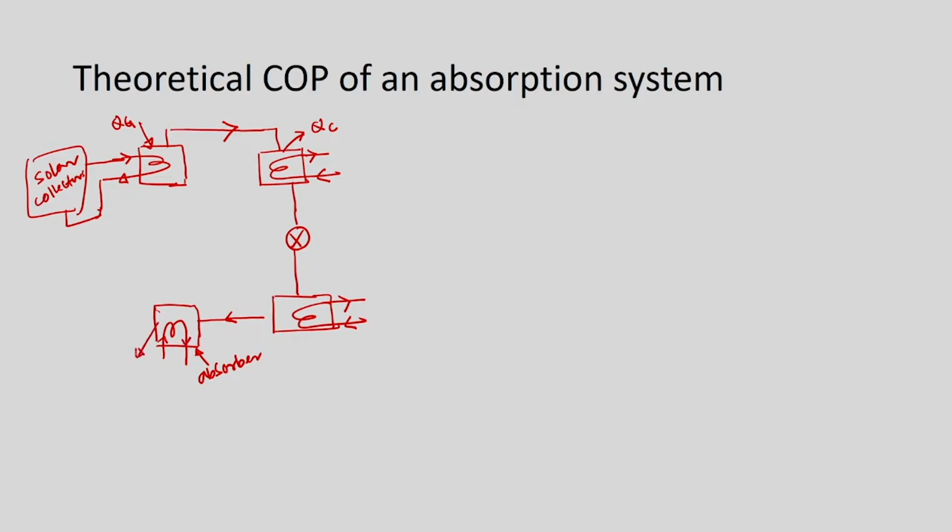So, this QA has to be removed, and here this QE, that much of energy, which is nothing but absorption of heat from the atmosphere. And then we will have heat exchanger here, and maybe we will have pump here. So, strong solution will have to move up, and we have a valve here, and it will go down.